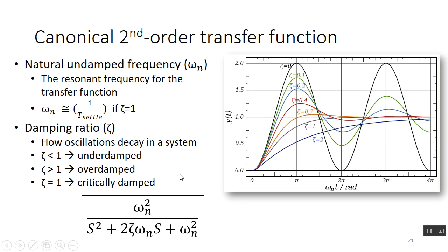That way it's one of those workhorse blocks that you can just drop in and say, I have no idea what my input's coming in as, but I know that this D to A can't move any faster than this. And so you can say the time constant of the system isn't going to be any more than 1/100th of a second. When you combine that with a rate limiter, and you can parameterize the rate limiter, then you get small signal and big signal characteristics, and it protects you from both.